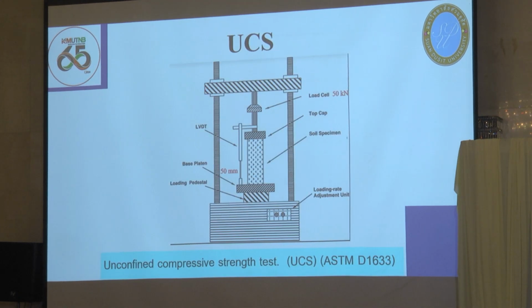For unconfined compressive strength, an LVDT of 50 mm and a load cell of 50 kilonewton were used, following ASTM D1633.